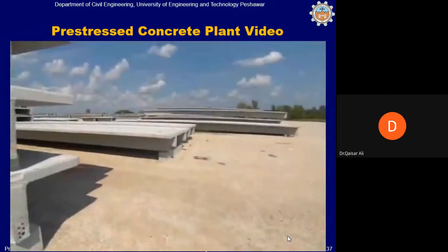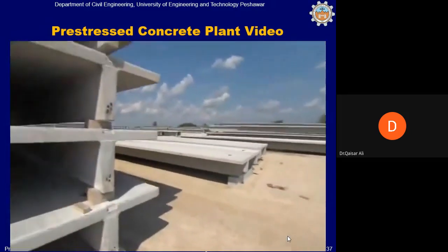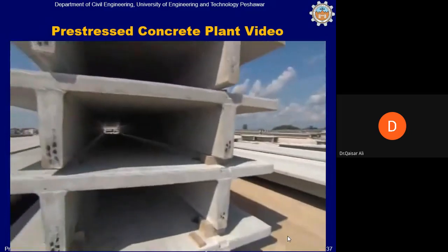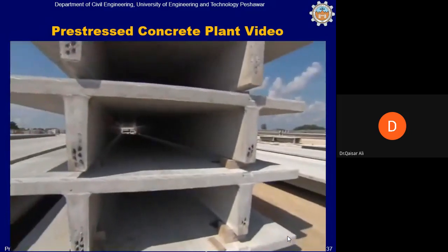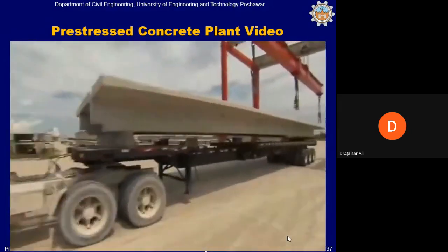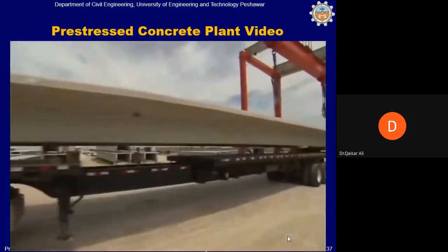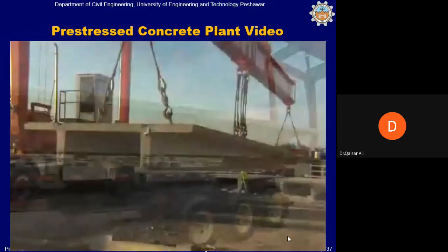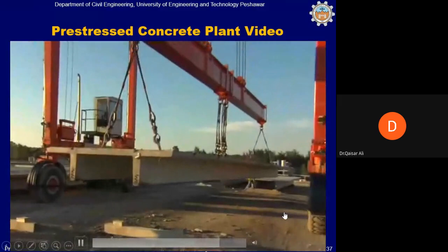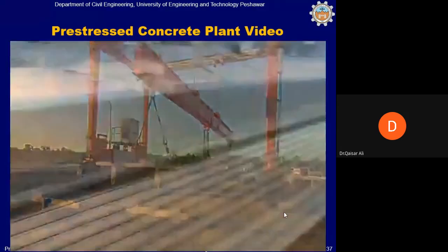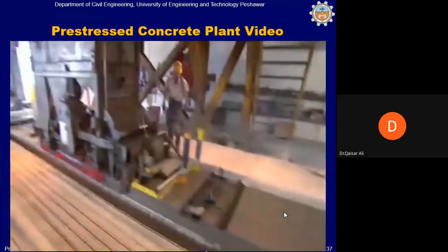After all the work is completed, the double Ts are moved into the storage area where they are typically stacked using appropriate dunnage located near the ends. When the job site requires the T to be shipped, it is loaded on a trailer and transported to the job site. What you have just observed is the process for making one type of pre-stressed product. These other types are made using essentially the same process.